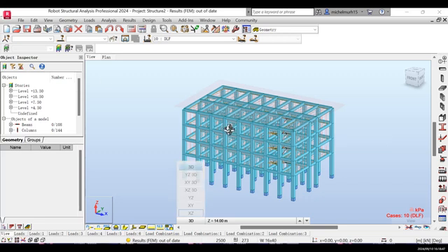As you can see, I'm going to reinforce my concrete according to the loads that I apply on my concrete building. First of all, we have the wind loads in two different directions. We also have the seismic loads with different eccentricity. Seismic load is just the earthquake. And we also have the self weight of the building, also called the dead load. It's the part of the building, so the building is going to carry that force forever. It's about the material and many other things. I listed everything before, so you can go and watch my video.